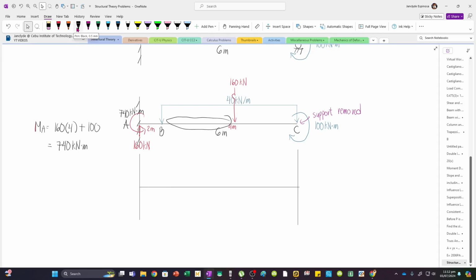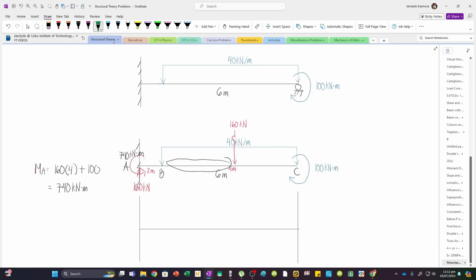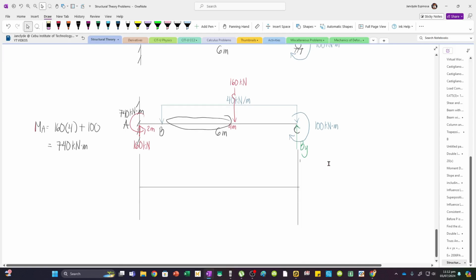First, by the way, we can put the supports back, and then we will just equate. I'll put BY so it's different. Now first, I will write the moment diagram by parts caused by BY. So we have here a straight line, and this is 6 BY, BY multiplied by the moment arm, which is 6. Since this load causes an upward rotation about this moment center, I have a positive area. That's how you can check. So this is actually about A.